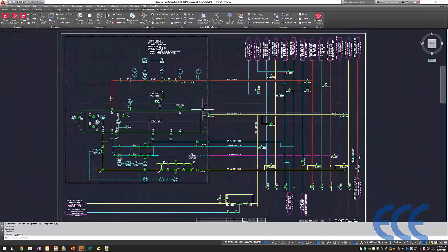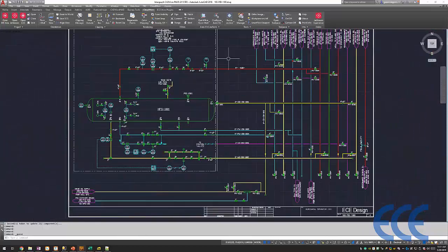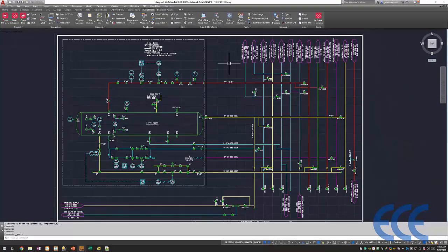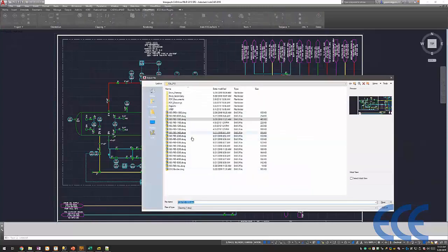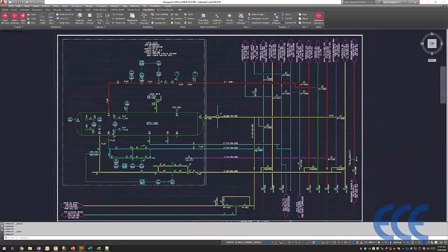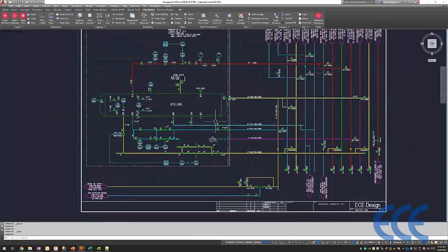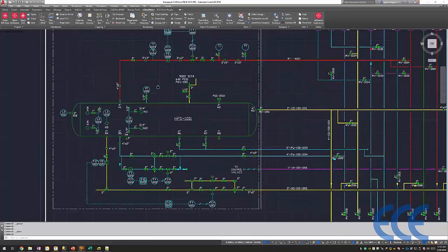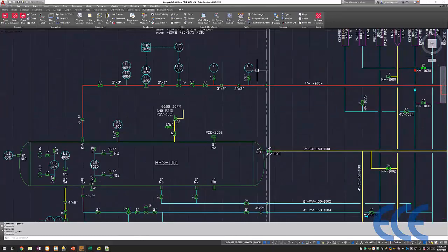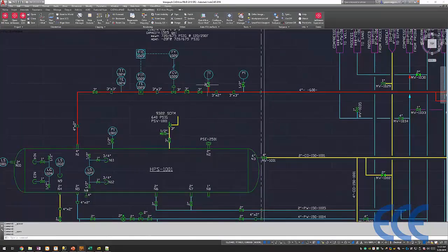Great. So I'm connected to a database currently. This is just one of many P&IDs that's inside this project. If I do a file open, there's like a dozen and a half P&IDs here. So I just open the first one, PID 1000, right? Just to keep it simple. So this has a vessel, and it has some PIs here. It's got some blank PIs as well, and TIs.